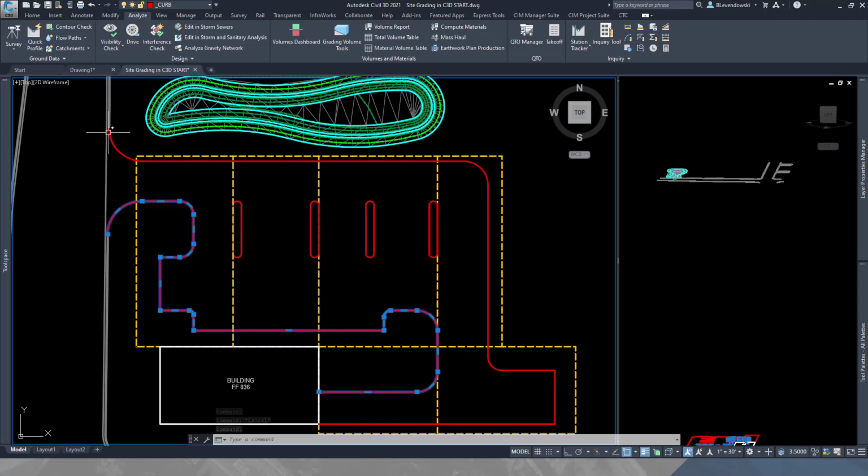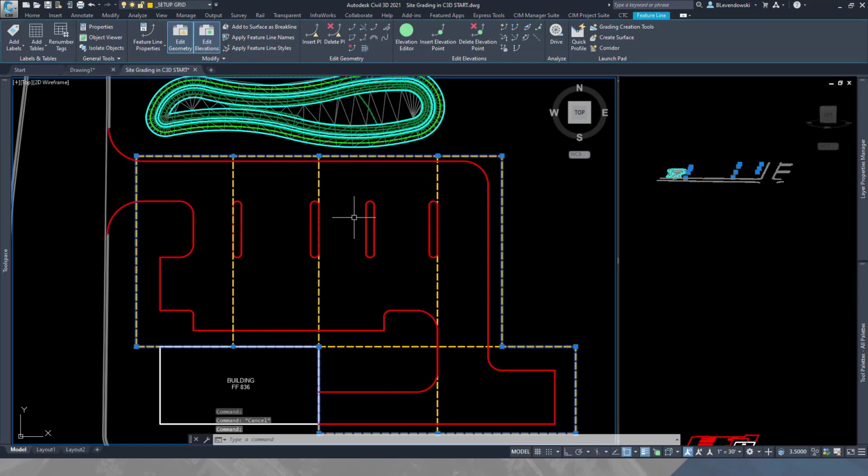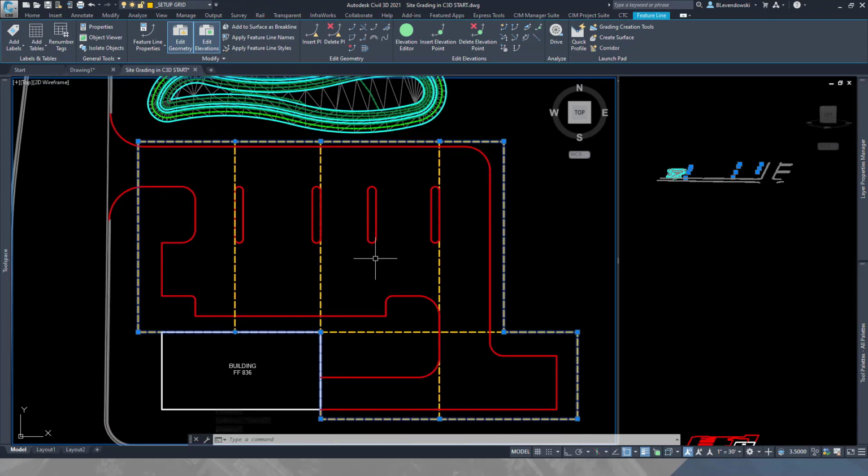because that's pretty straightforward what those elevations should be. But the rest of this, I'm going to control all the elevations from a surface built from these very simple feature lines. Okay? Now you can edit these as you see fit. Start out by drawing a polyline like we did a pond, and then start to envision where you'd have ridges or swales in your parking lot, and then draw crossing feature lines there.